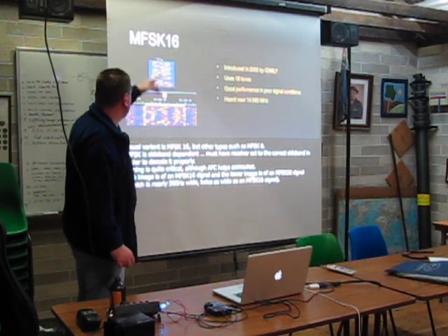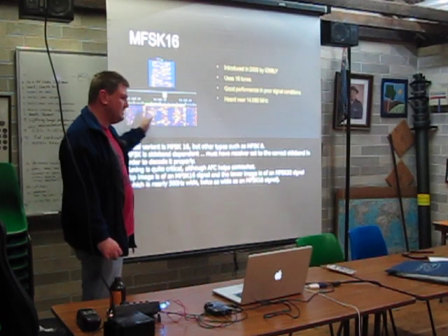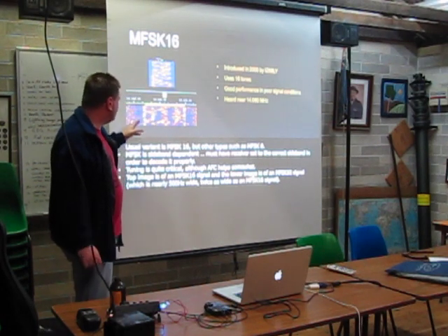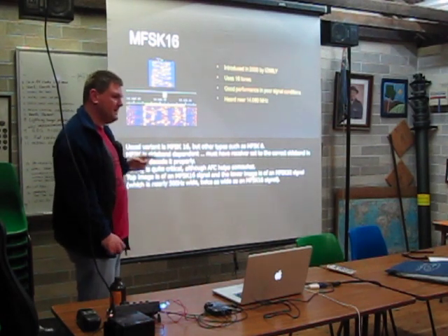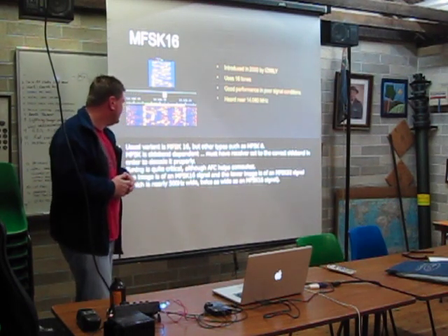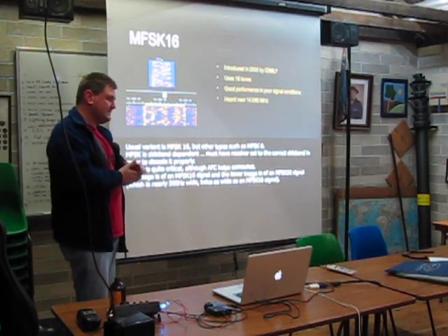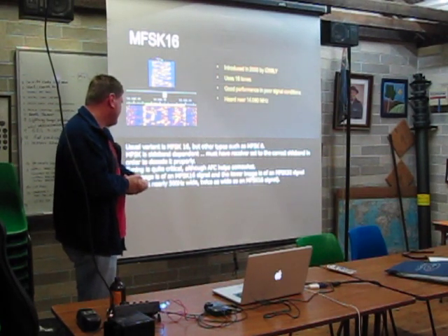So here we have MFSK16. We talked about radio teletype where you've got 2 tones. Well, you can actually use more than 2 tones, and that allows you to cram more information into the channel. And so you can get a faster transfer rate.